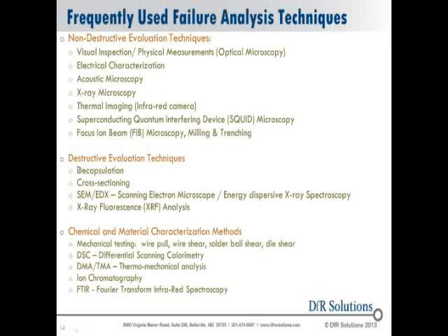Now, we then move into our destructive evaluation techniques. Decapsulation, where you dissolve away the outer protective package or housing of an electronic device so you can directly inspect its core technology or active element. Cross-sectioning, another way where we will cut into a system or device or a circuit board assembly at various depths, possibly a sequence of depths, in order to see what is going on at different planes into the structure.